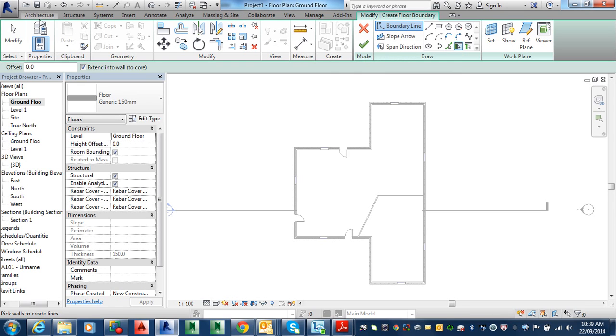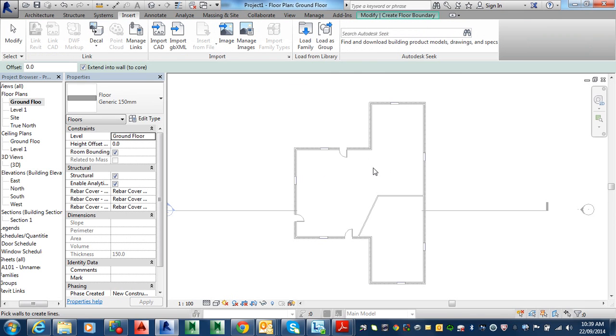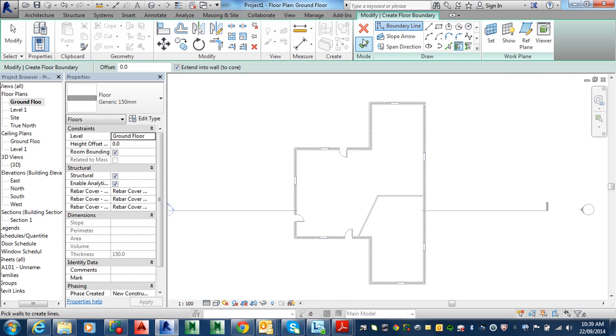Sometimes you end up clicking somewhere else to insert something, and then you think, okay, well, how do I get out of that sketch mode? You've got to always remember that there's a little green tab up here. If there's a green tab up there, go look there first. Because it's usually asking you, what do you want to do? You want to tick it or cross it, you know. So anyway, we'll just continue on.